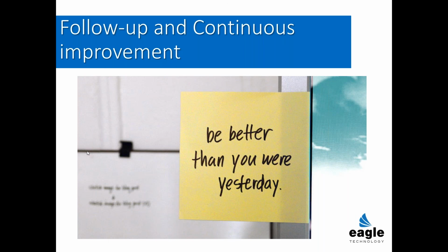Typically, an organization that doesn't have a CMMS in place is probably doing a lot of break-fix or reactive maintenance. And in some cases, that's all they care about, depending on whether you are owner-occupied or tenant-occupied. But in terms of the CMMS, it's critical that you have follow-up and analysis of the data on a continuous basis. You can refine work types. You can refine estimated times on jobs. All of these things will come so that ultimately you can get to something called predictive maintenance, because there is no way to get to predictive maintenance until you have quality preventive and demand maintenance information.